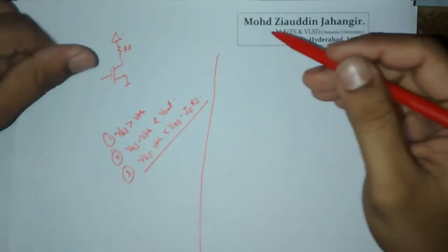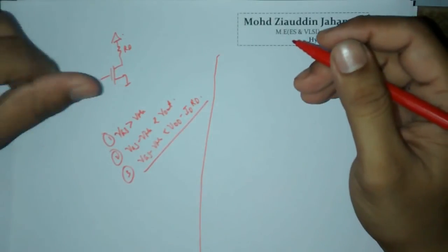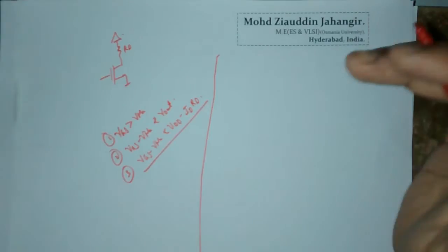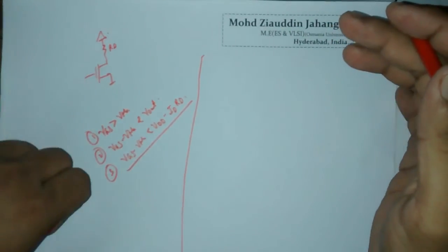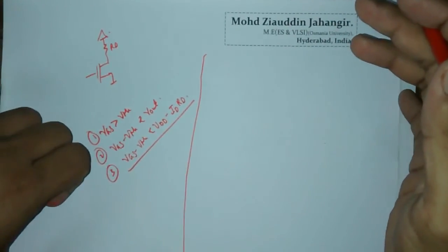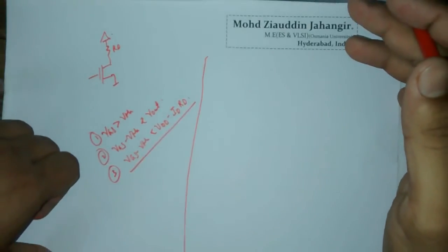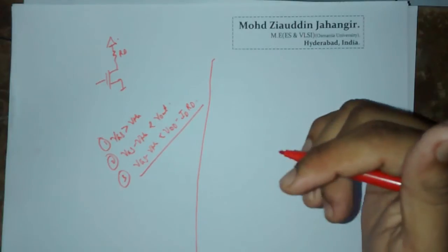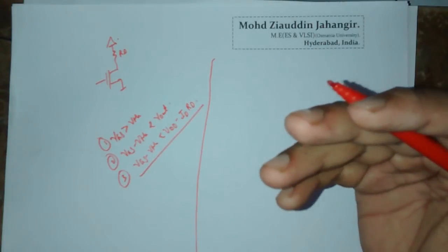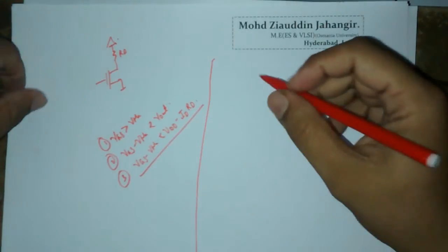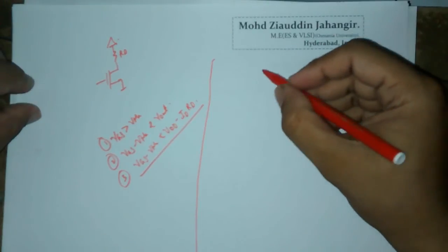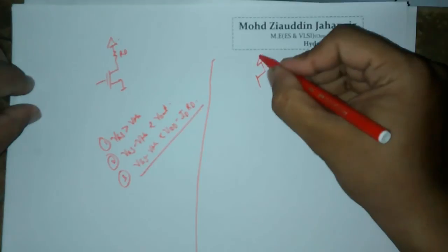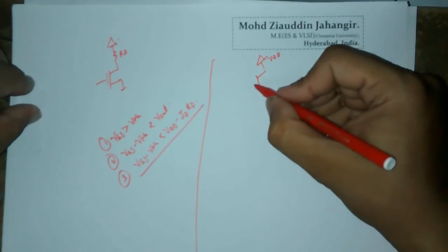So here what we talked about was a very simple amplifier. We used RD here, whereas when you go for fabrication, ICs don't have resistors. That means you cannot fabricate resistors so easily in the IC. So how to get a common source amplifier circuit which is suited for fabrication? For that purpose, what you can do is replace that RD by a